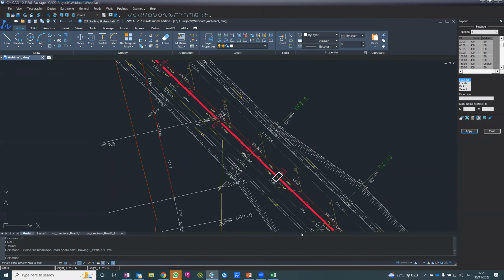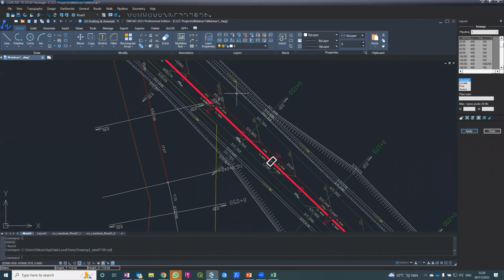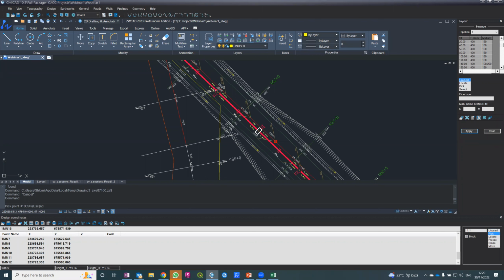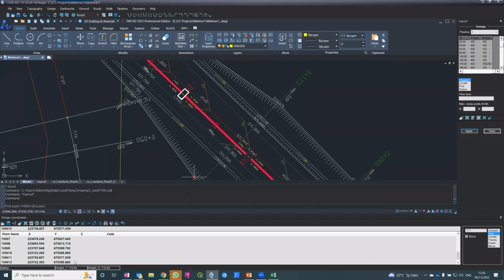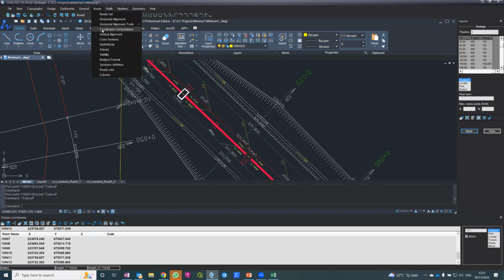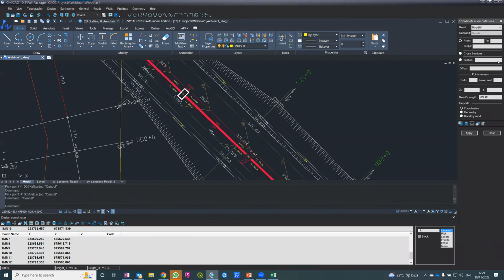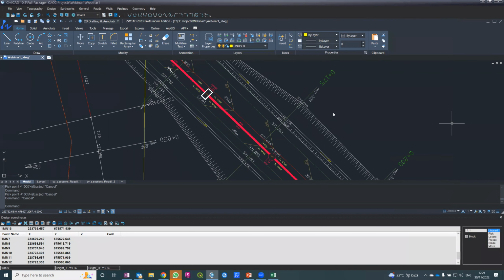Assuming you have finished with your road or pipe design, is there an export option to LandXML for the surveying crews to stake out? Okay. As I said, we have export to IFC. In the past, we had some exporting to LandXML, but we abandoned it toward the IFC. So the direction is to export to IFC. About setting out, the best thing is to take the AutoCAD, go, for example, to design coordinates, put a pick here, and start picking, creating points. This is all our construction people do. They either pick points here into the TXT automatically and export for setting out, or they use roads for roads. We have earthworks coordinates computation, where you can automatically create a list of XYZ along or at a certain point or at the side sticks and so on for setting out. So I think this is much easier.